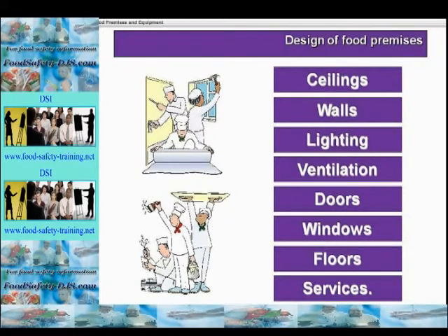Ceilings should be washable, non-flaking, smooth, easy to clean, resist condensation, light-coloured, fire-resistant, coved. Suspended ceilings are an advantage. Walls should be smooth, impervious, non-flaking, durable, light-coloured, coved. Avoid voids and internal cavities which could harbour pests. Make sure the walls are easy to clean and disinfect, and protect as necessary, for example the corners of the walls, perhaps with some metal strips.